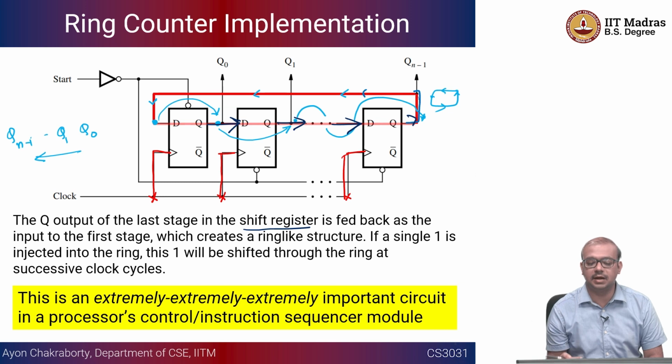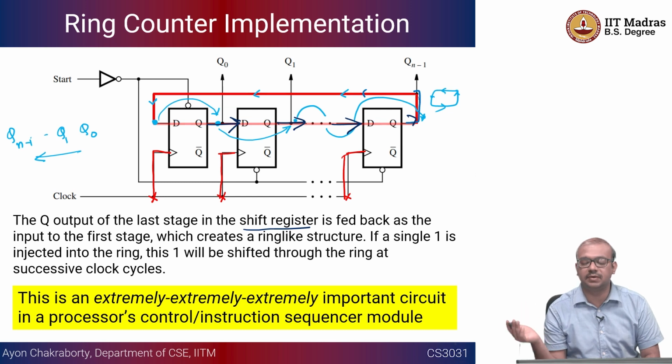Typically that kind of shift operation is often called a rotation, or rotate. So you shift, but the most significant bit on the right hand side is going to go to the least significant place, or vice versa, based on whether it's a right shift or left shift. They will call it a right rotate or a left rotate.